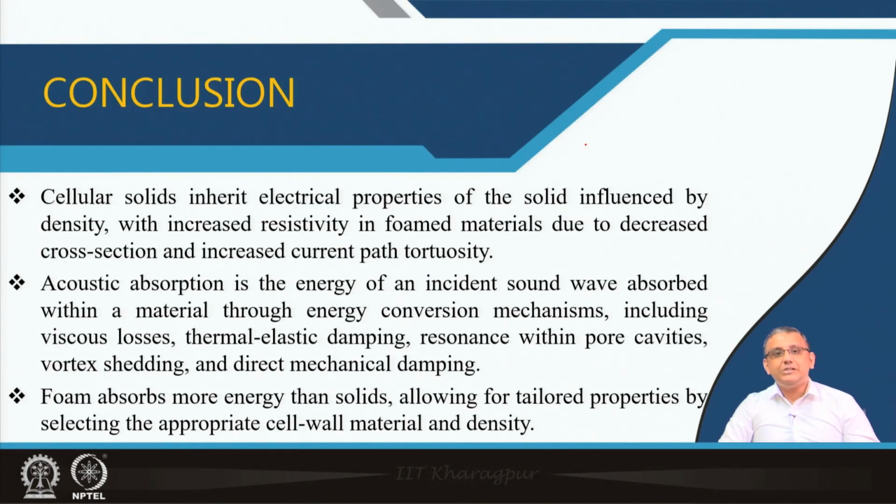So, this brings us to the end of today's lecture. We learnt about 3 different properties in this lecture. We first learnt about the electrical properties, and there we learnt that in case of foams, the resistivity of the foam depends upon the foam relative density. The lower the relative density, the higher the porosity, and the higher the resistivity of the foam, and this is applicable for insulation applications.